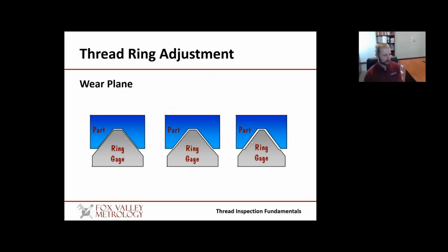Now, this might be imperceptible to the eye. I know it makes obvious sense here looking at a PowerPoint, but in reality, it's going to be very difficult to see this. That's why, of course, regular calibration of your thread rings, and of course, even your thread plugs too, is strongly recommended.